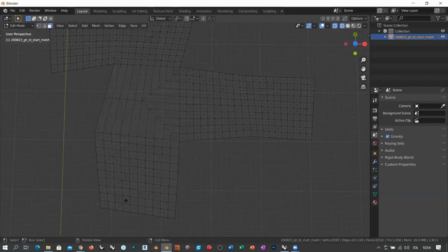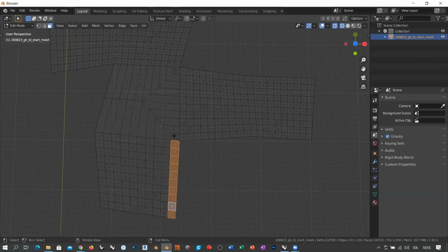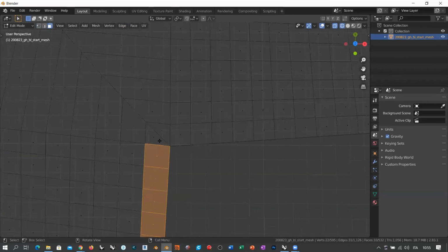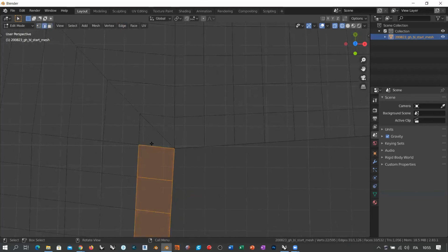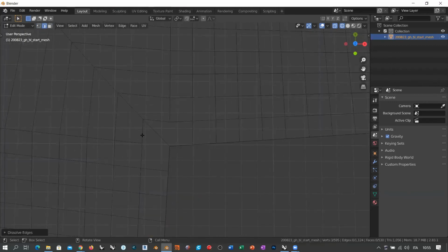Just to double check, you see that now if I select this, this loop runs on the left of this corner, but this is turning, and this is stopping because it has triangles. Okay, so we must convert also this thing in quads. And in order to do this, we should dissolve these two here. So if I right click and dissolve these edges, I have this. But this is a problem because these are not quads. Now these are pentagons. They have 5 edges. And also this one, it has 5 edges.